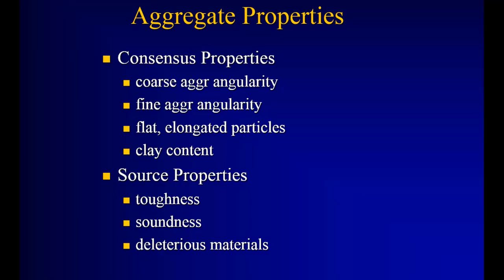We handle aggregate a lot of times during the production of hot mix asphalt, from not only the pit, but the haul to the plant site, the stockpiling operation at the plant site, from the stockpiles to the plant through this big drum I mentioned, and then out to the road. And then the torture doesn't end there for aggregate, because once it's windrowed in front of the paver, it goes underneath the vibrating screed, and then of course is subject to the impact forces of steel wheel vibratory rollers and rubber tire rollers and so forth behind the paver.